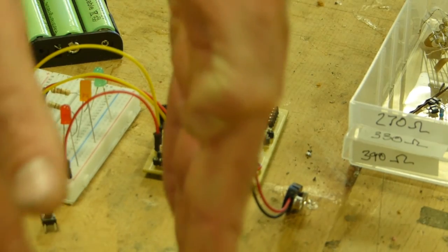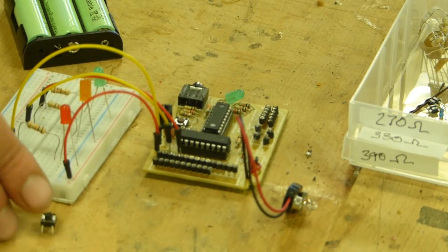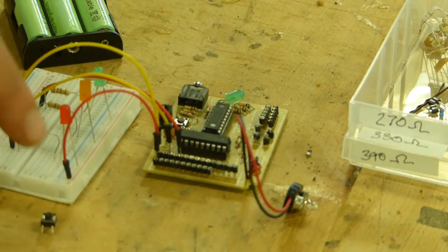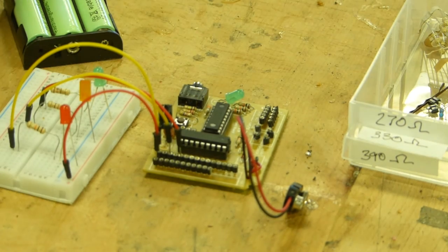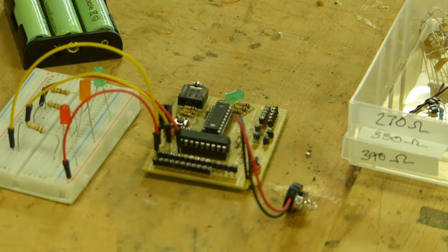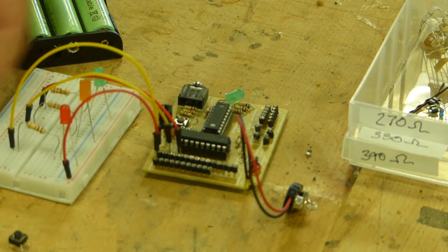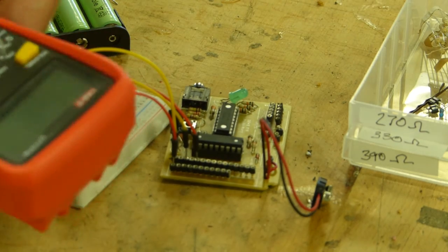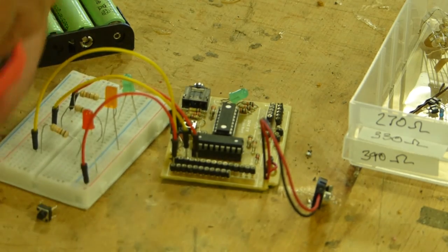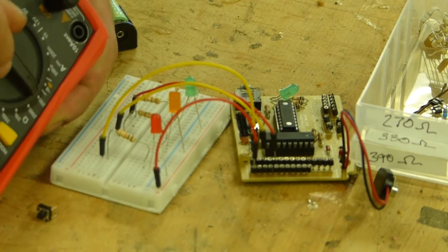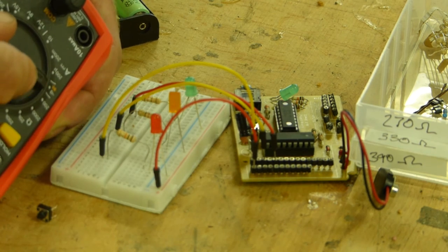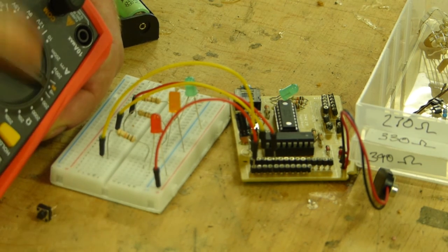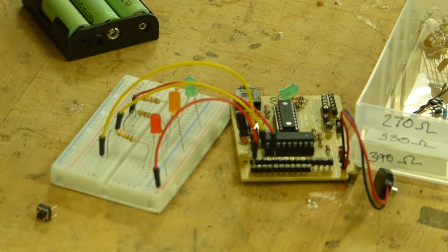They're the two that make an electrical connection when you push it. So they're not connected together, but when you push it, they are. So it's just an important way of remembering it. But remember, if you can't figure out which way round they go, just use a continuity tester on the voltmeter. So that way you can just tell by touching the two legs if they make a beep or not, if they're joined.